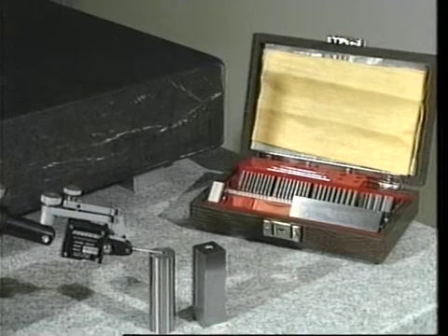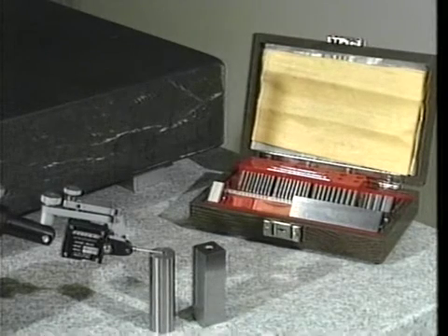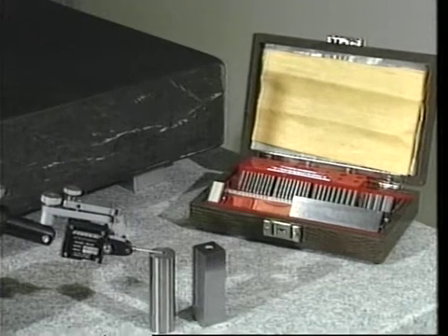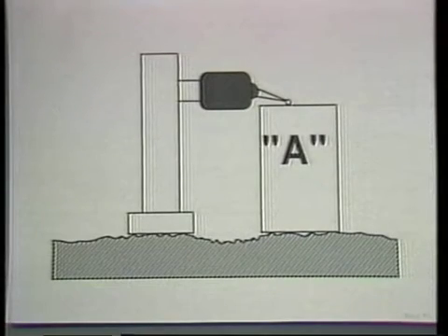Consider the height measurement of this specimen using a surface plate and an indicator. The base of the indicator stand and the bottom of the specimen will provide some averaging or filtering of the high frequency surface waviness. Therefore, we should concern ourselves with measuring the very low frequency waviness, which will influence the repeatability of the height measurements over the area of the surface plate.